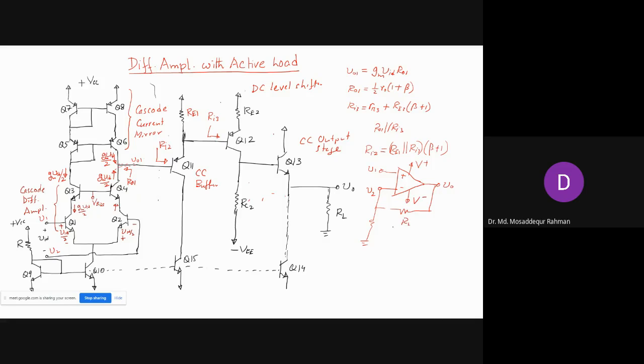This we call R2 and R1, and V1, you apply the signal. What will be the closed loop gain? If this is in non-inverting configuration, 1 plus R2 by R1, or you can ground this side and apply the voltage here. So that is how you control the gain.